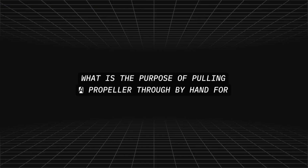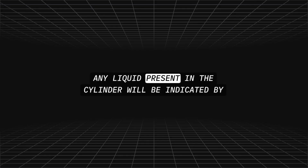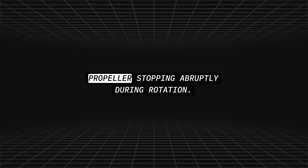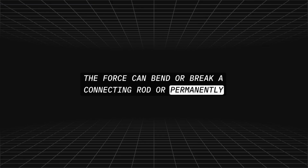What is the purpose of pulling a propeller through by hand for 2 or 3 revolutions prior to starting a radial or inverted engine? To detect hydrolock. Any liquid present in the cylinder will be indicated by abnormal effort required to rotate the propeller, or by the propeller stopping abruptly during rotation. What damage is likely to occur if excessive force is exerted on the crankshaft when there's liquid lock? The force can bend or break a connecting rod, or permanently damage the cylinder.